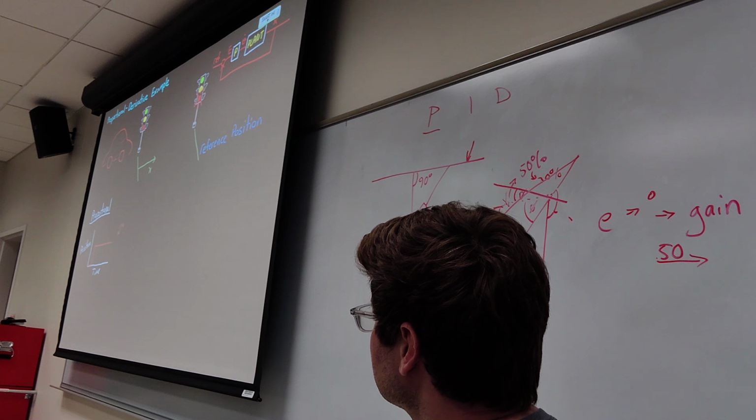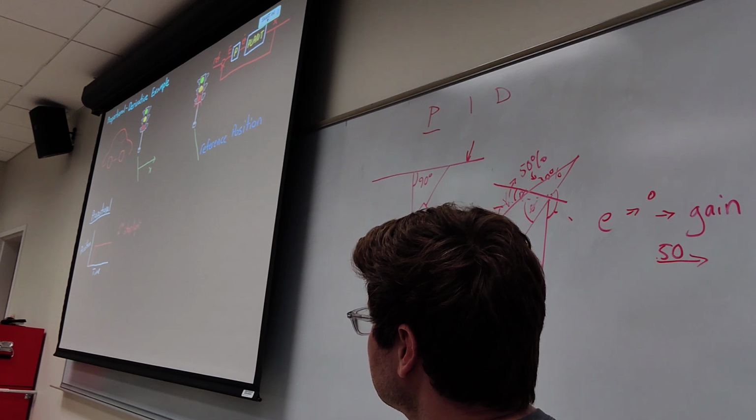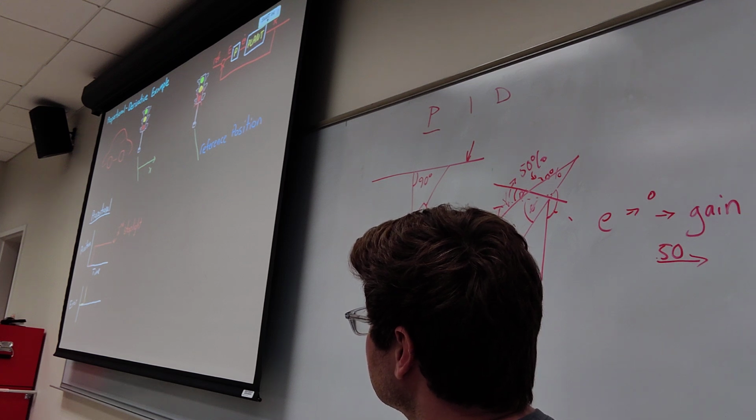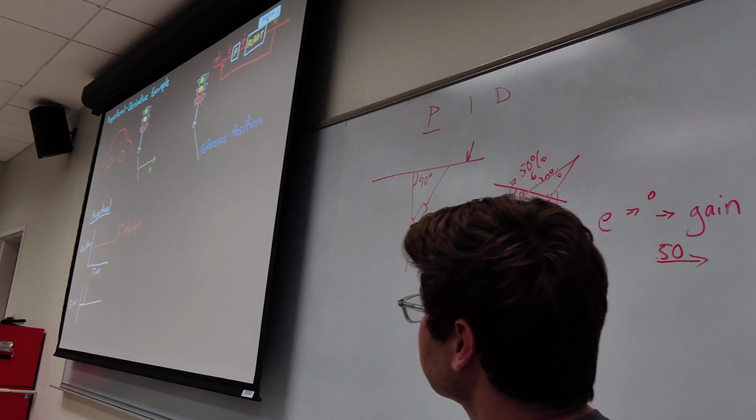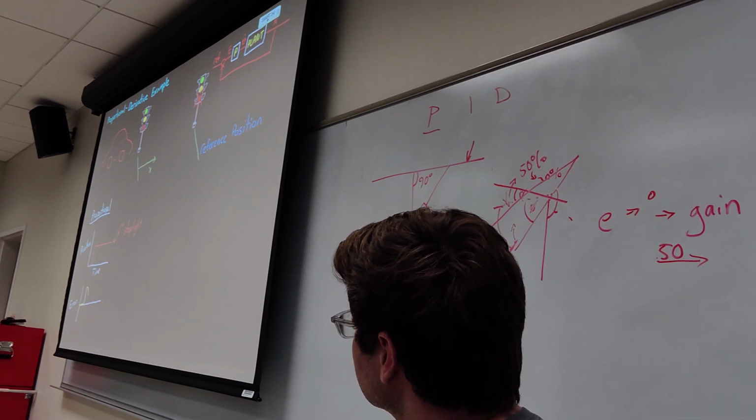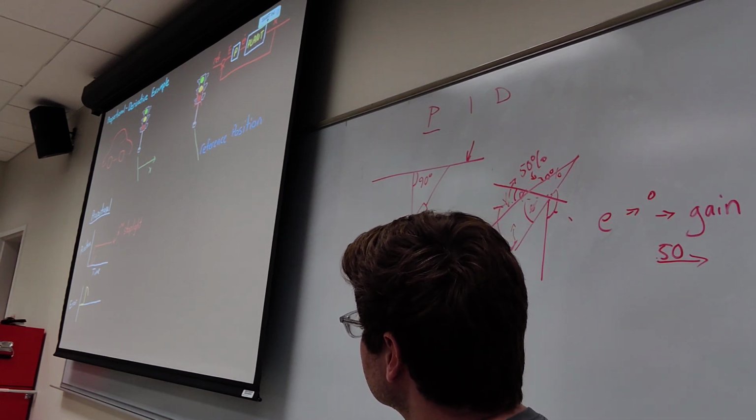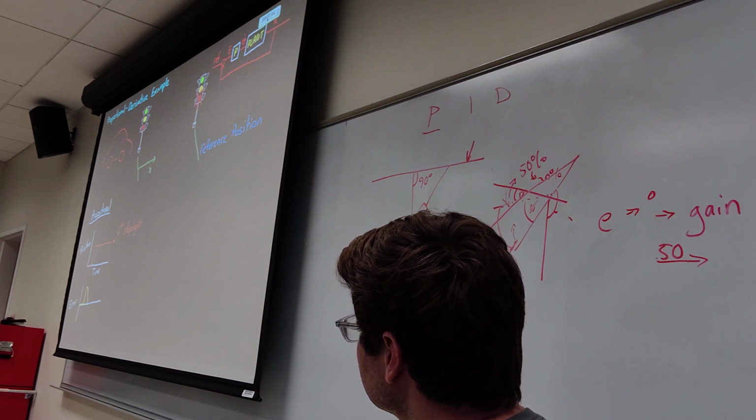Again, your reference position would step up to the position of the second stoplight. And since initially your error is large, you apply a large proportional change in pedal angle. The car begins to accelerate, and as you get closer to the stoplight, the error gets smaller and smaller, and the magnitude of the change of pedal also gets smaller. Eventually, you arrive at the light, and right when you're there, the error goes to 0 because you're at the position you want, and you stop changing the angle of the pedal.